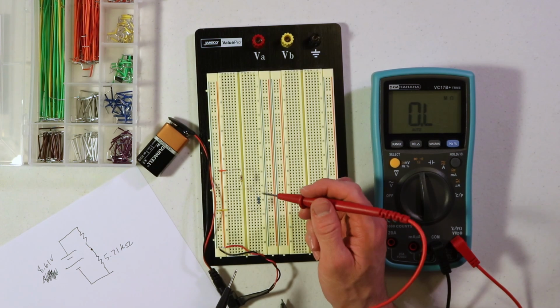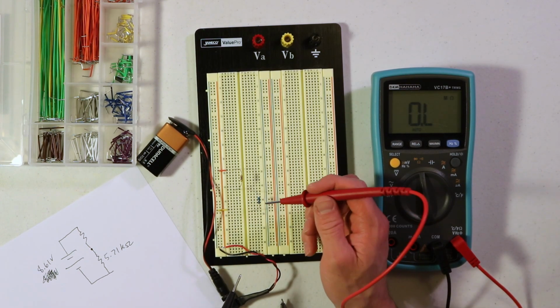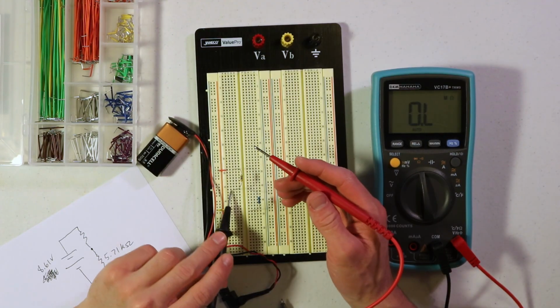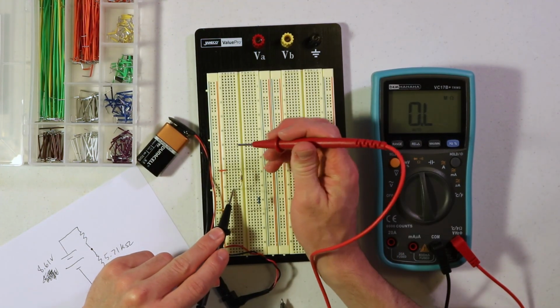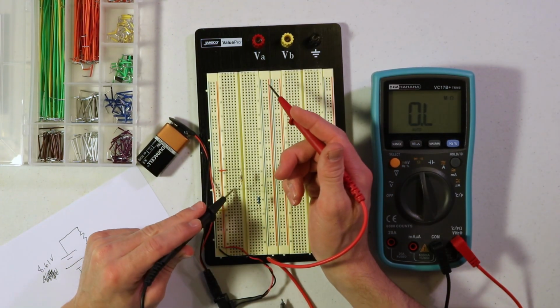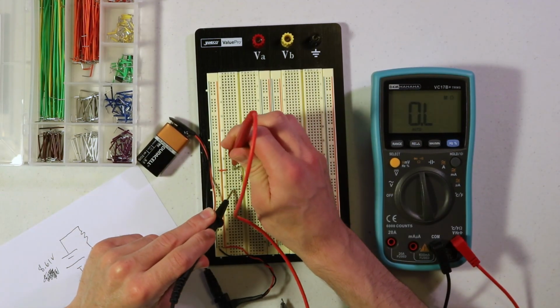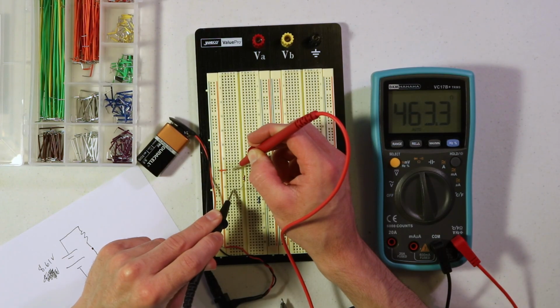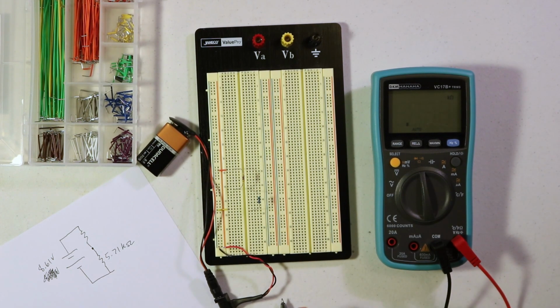And I guess I didn't mention it, but the reason you pull it out is that if you don't, then you're measuring the resistance within the whole circuit, which will not give you an accurate reading, so you actually have to disconnect it from the circuit. And it's okay now if I want to measure here, because no current is going to be flowing and nothing else is connected. So now we see 463.2 ohms.